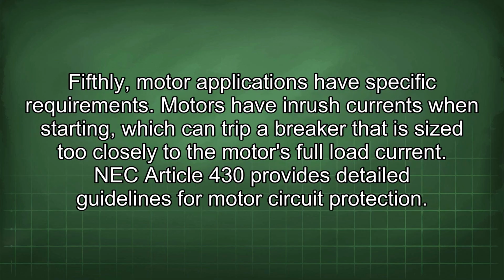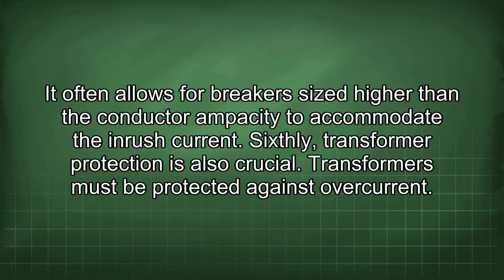Fifthly, motor applications have specific requirements. Motors have inrush currents when starting, which can trip a breaker that is sized too closely to the motor's full load current. NEC Article 430 provides detailed guidelines for motor circuit protection. It often allows for breakers sized higher than the conductor ampacity to accommodate the inrush current.